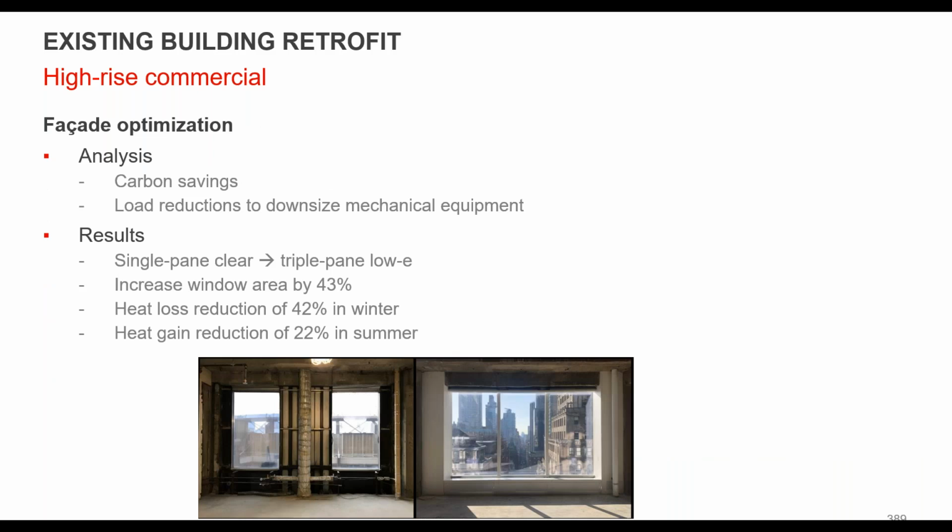So the facade, just to show before and after, the left is before, after on the right. So again, they added a whole another basically bay of glass. They took out these high pressure risers, much cleaner look. They lowered the sill a little bit for a much higher window glazed area, better view, better daylighting.